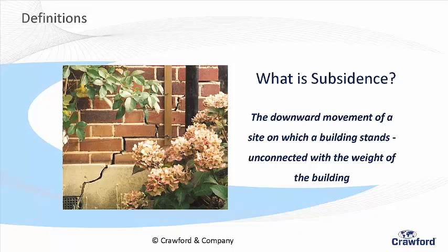Rotational. Can you see that brick there? It's just proud of that brick there because it's rotated out. And the ground here has shrunk. It's not connected because the building's got heavier. It's dropped because the soil conditions have changed. Right? So bear that one in mind. I'm going to come back to that.